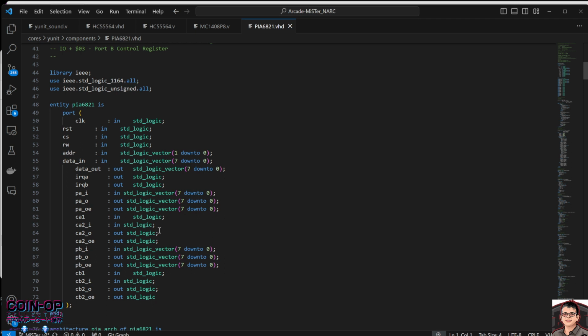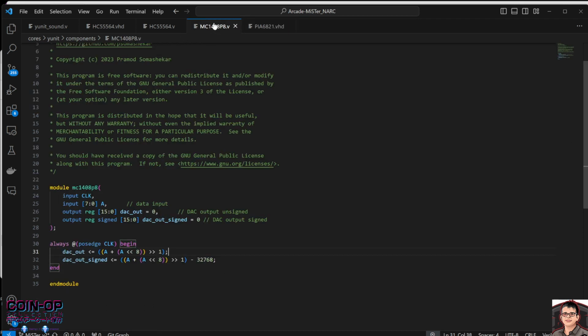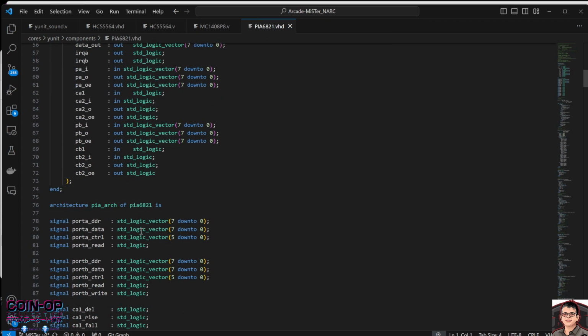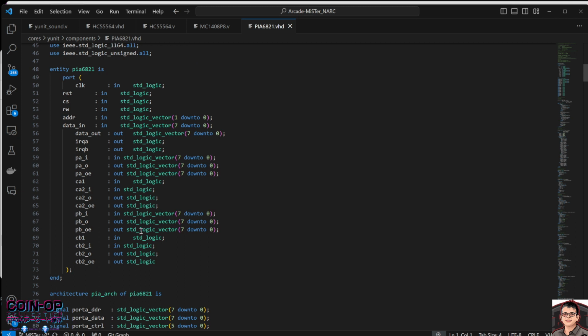The data outputs from here go directly into here, and it's used that way. All of this implementation is correct, but it's a weird module because it's very hard to follow when these signals are triggering interrupts, and when the interrupts get triggered is a big problem on this board, I found. So I had to adjust the timing of that carefully and monitor it in the simulation bench more to figure out what timing it's using.